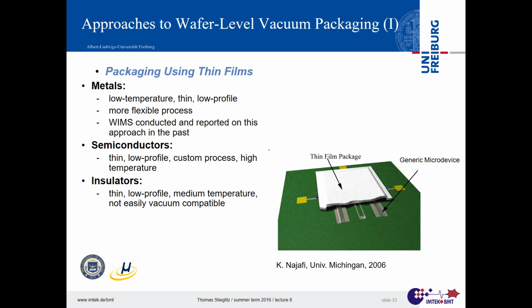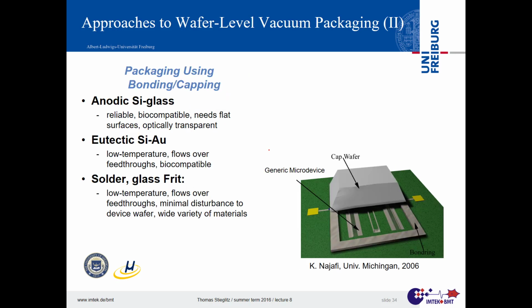That's where you have to take care. The good thing is you have really a thin additional layer on top, so it does not get too thick there. You can really put a cap, so something massive, a silicon cap or glass cap on top of that, with the question of how to get that connected, and that's either then silicon-glass anodic bonding.